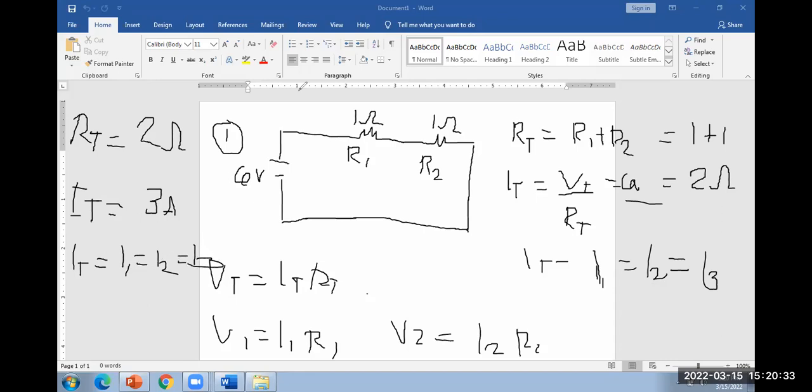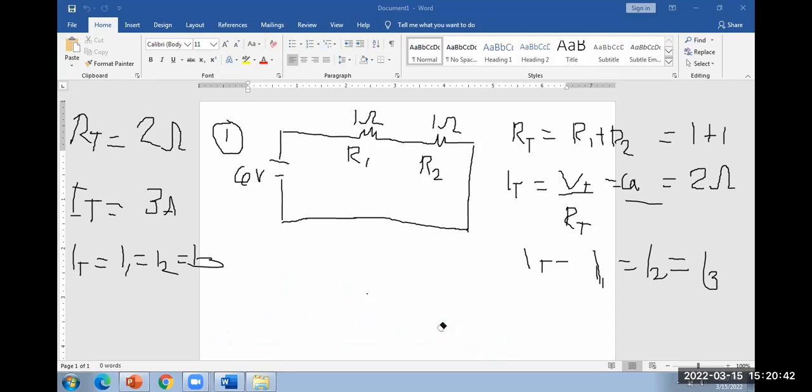Then, what is the total voltage drop? So, ano naman yung voltage drop natin? So, voltage drop is B1 is equal to I1 R1. Then, B2 is equivalent to R2 I2. So, ano ngayon ang voltage drop natin? Tig ilan daw sila? So, B1 is equivalent to I1 times R1, which is 3 amperes times 1 ohm. So, ilan yan? 3 volts.